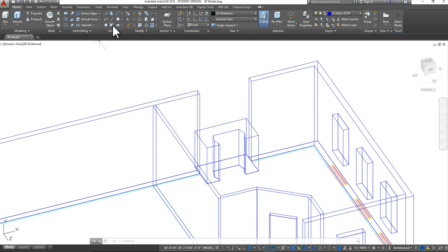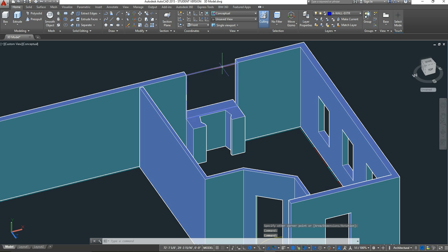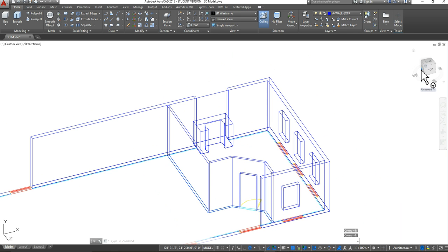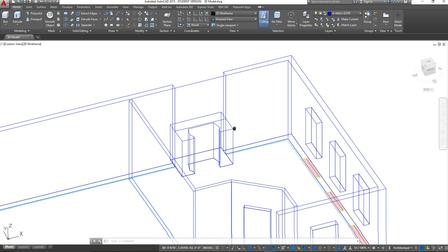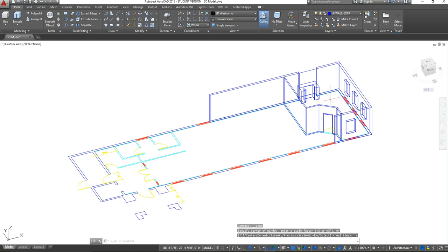And then I'm going to select my rectangle tool and create a rectangle from that endpoint over to that endpoint there. Okay. Again, if you're in your conceptual, you should just see, if I highlight it, I've just created a rectangle where I'm going to start to close that portion up. So now that I have that there, I'm going to again go back to my world coordinates. Again, that just allows you to hover a little bit better when you're in your world. But when you're drawing, you just want to specify what plane you want to work off of.